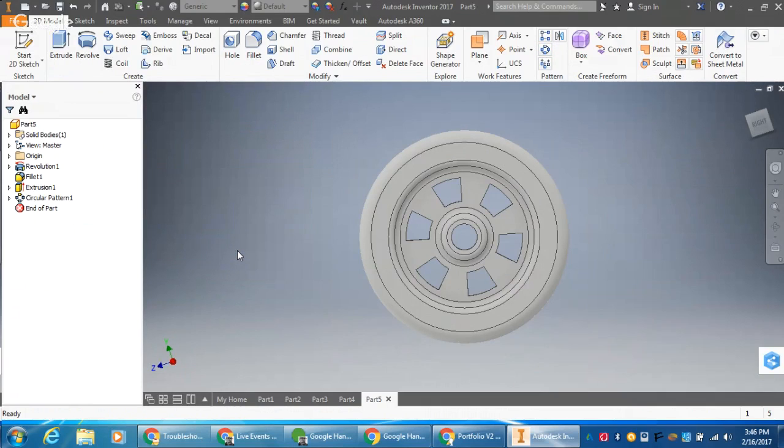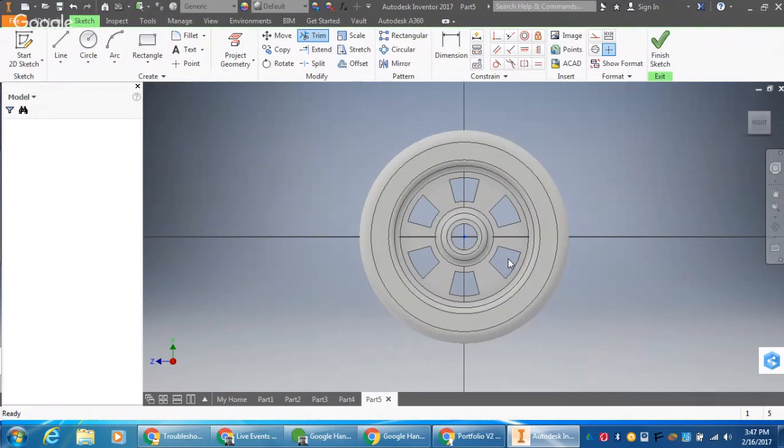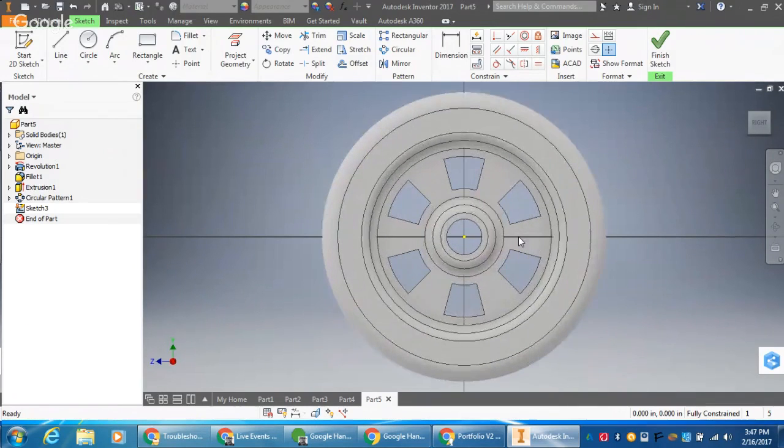And that's it. The last thing that we have to do is put this little peg on here. So I'm going to go to this surface, new sketch, and since I built it this way and offset this by 15 degrees, I automatically have some place to put down this little peg, because it's right in between these. That just makes it easier for me to line everything up. So I can actually start on this axis, which makes it a lot easier.